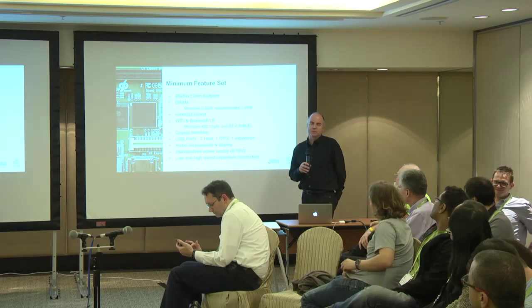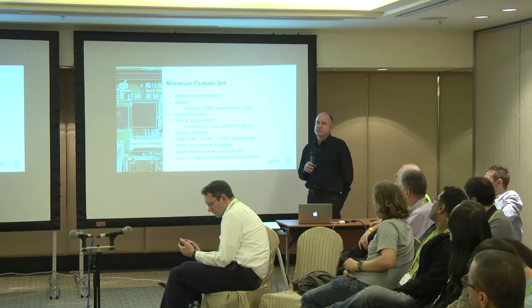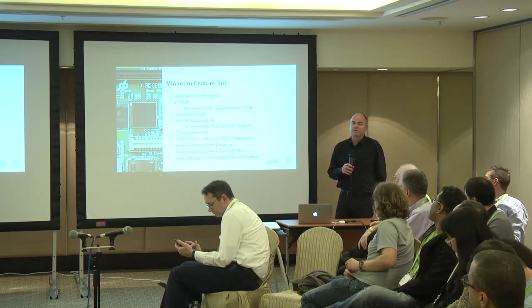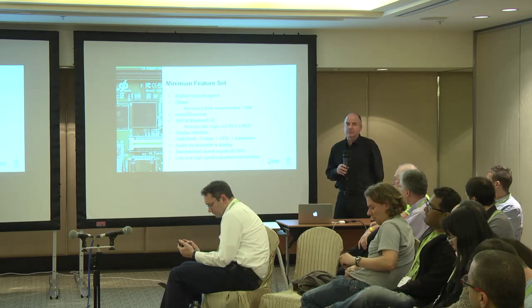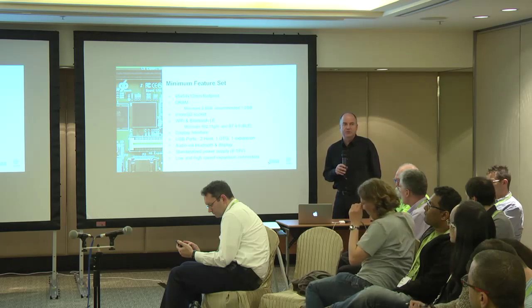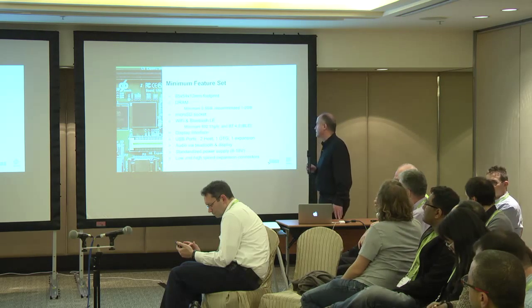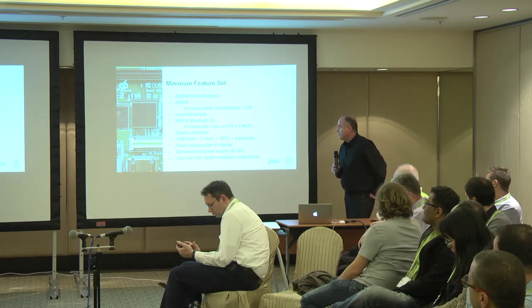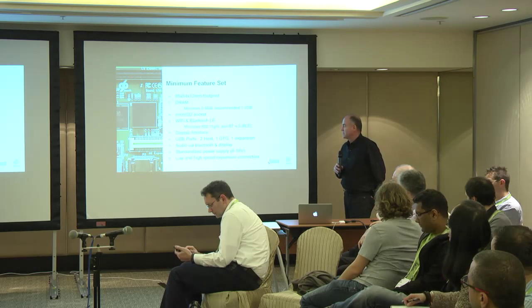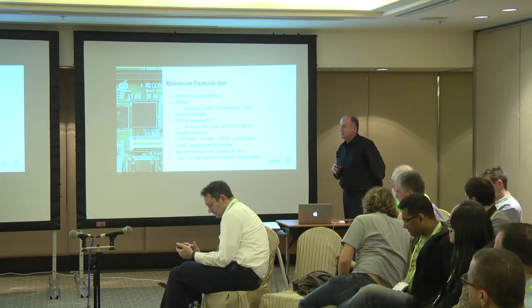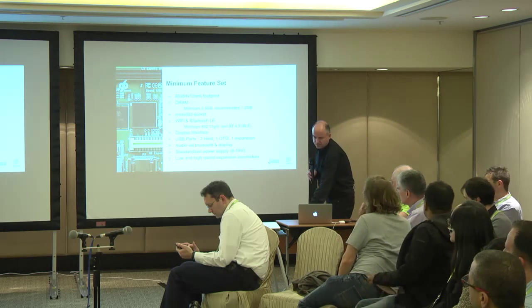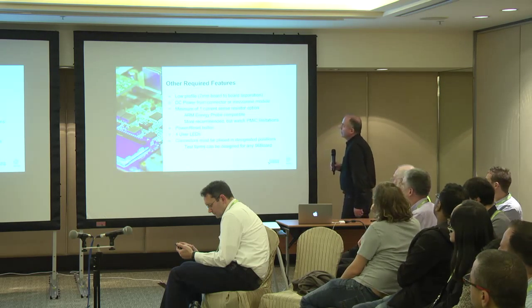That will change once we go to Type-C connectors, because on a Type-C connector you can get 60 watts of power into the board. So that's something that we allowed in the spec for the future, to actually use USB Type-C for the power supply. But there is an external standardized power supply, notionally 12 volts at 2 amps. And standardized low and high speed connectors, which we'll talk about in a moment.